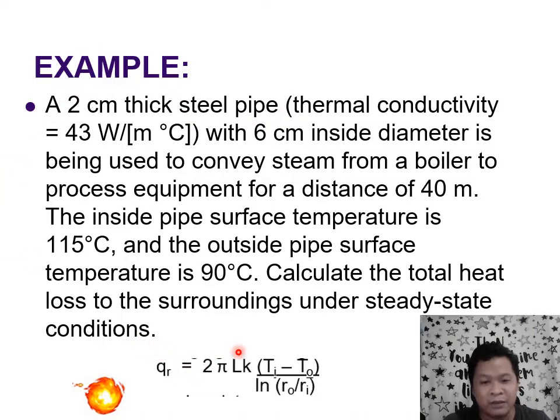And we just use that dito sa equation. You have your thermal conductivity K. So it's much higher because it's a metal. Okay. And then after plugging this, you get a value of around 529 kilowatts. So that's a lot of heat.